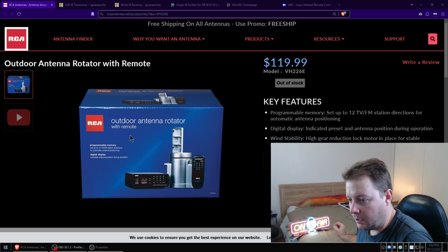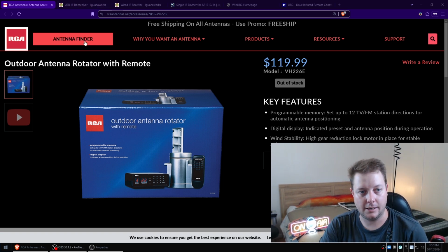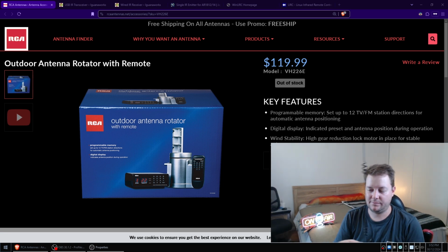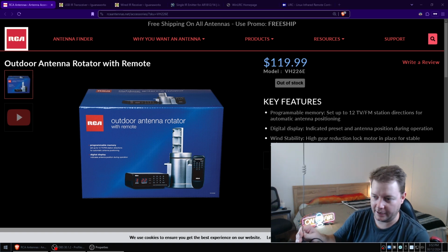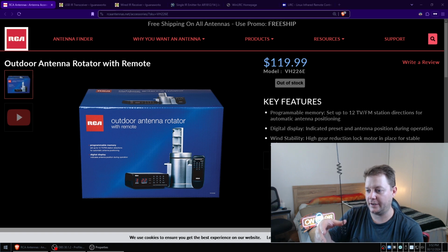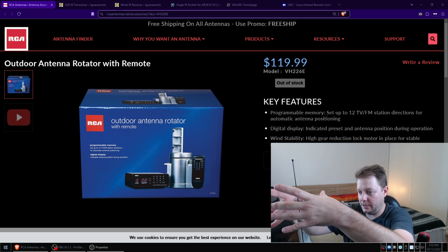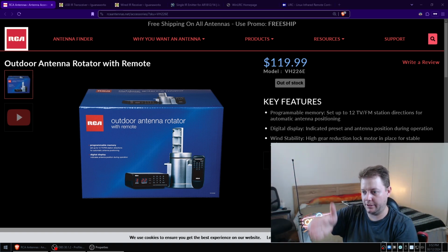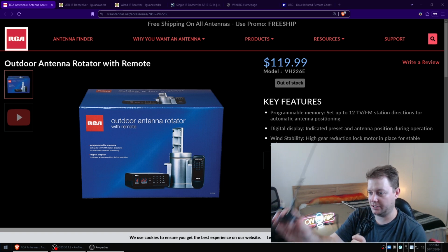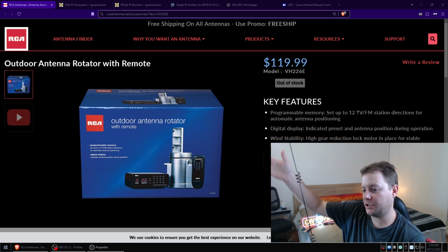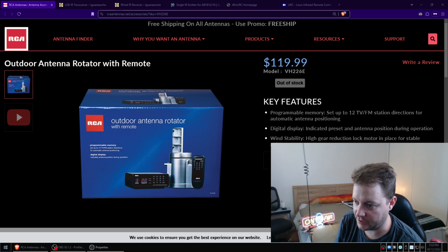So, this thing here is called a vertical antenna. It's supposed to be for a car, obviously. It's got a magnetic mount and stuff like that, but the frequency and how you mount it's not important. All we care about is the fact that it's an omnidirectional antenna. So the radio waves come out in a bubble in all directions from this antenna here, which is fine because this doesn't need to be pointed in a certain direction. You can just stick it on top of something, and no matter what direction the source or the destination of the radio waves are from, this antenna will hear it if it's in close enough proximity, right?